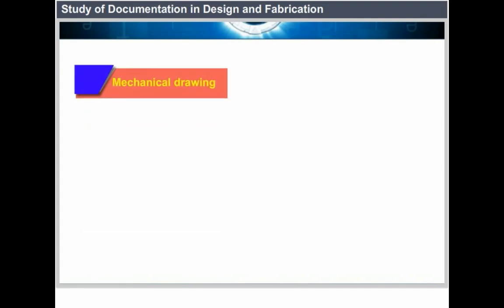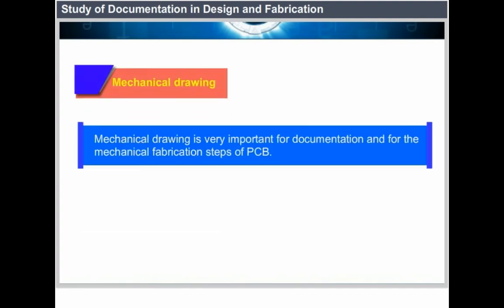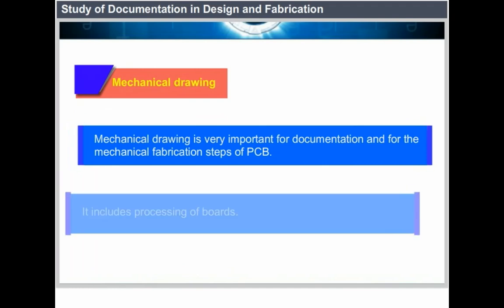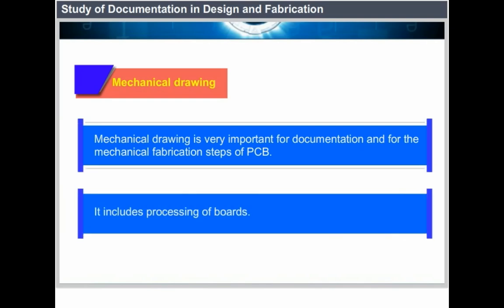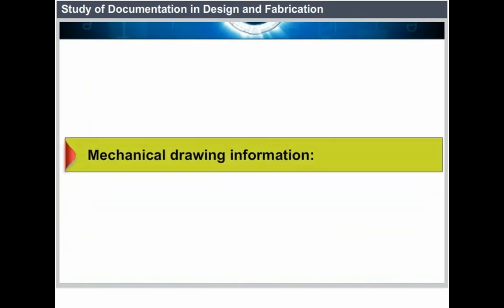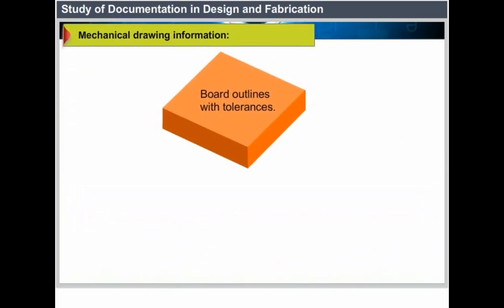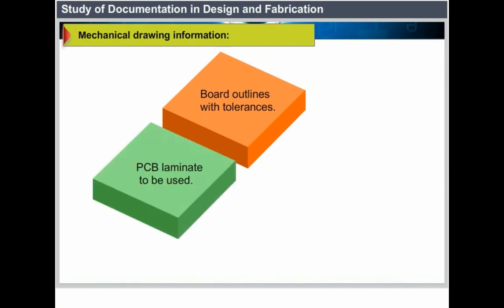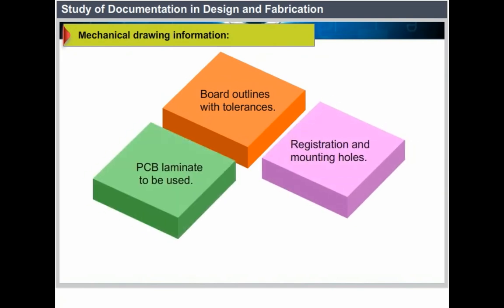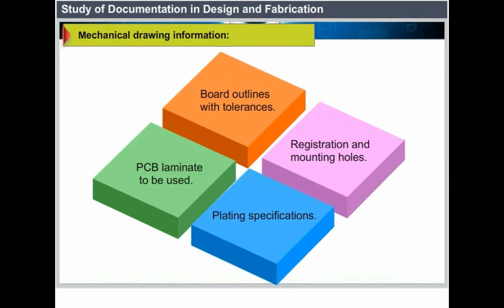Mechanical drawing. Mechanical drawing is very important documentation for the mechanical fabrication steps of the PCB. It includes processing of boards. Mechanical drawing information: board outlines with tolerances, PCB laminate to be used, plating specifications, registration and mounting of holes.